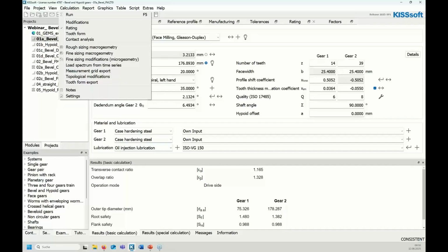If vacuum hardening is applied, distortions can be smaller, and also the DIN class can be better. Whereas for grinding, you end up, I would say, in DIN 3 to 4. So this is a disadvantage of lapping. It's quite a nice option for hard finishing, but the achieved accuracy class with lapping is unfortunately a bit worse than for grinding.